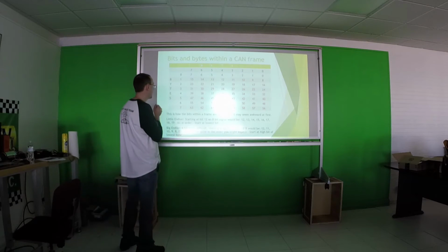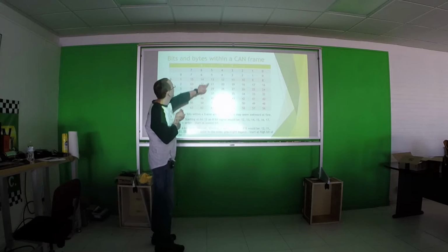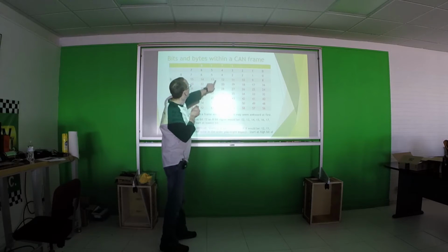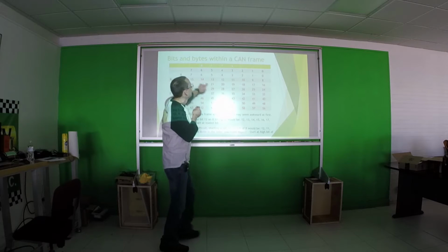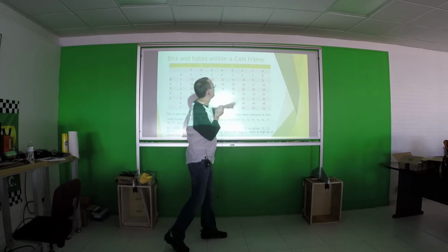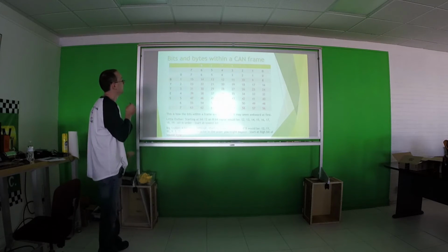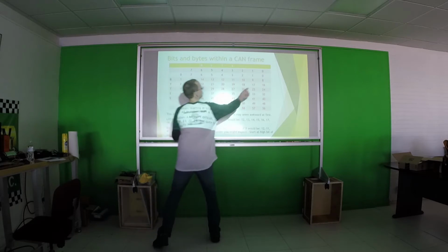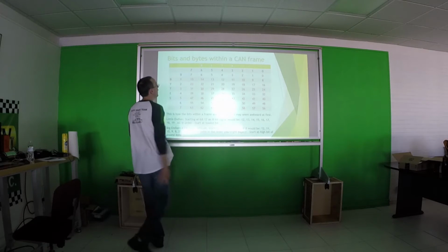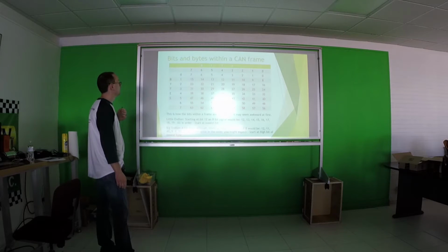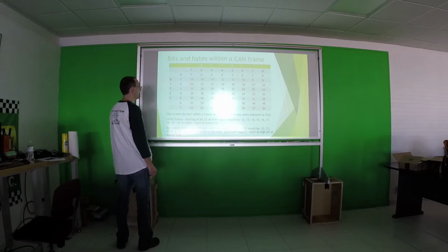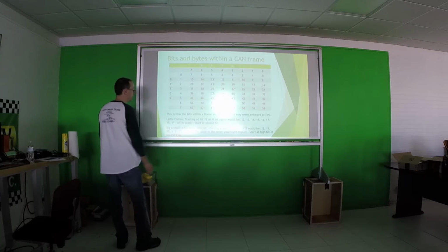And in a DBC file, complicated as it seems, if you start at bit 12, let's say up here, and you're going to store an 8-bit number, which unfortunately they sometimes do, this will go 12, 13, 14, 15, start back over here, 16, 17, 18, 19. That's where the data will be stored in little endian mode in DBC. You hope that they won't do that, because normally if you store an 8-bit value, you'll say start here and end here, and it doesn't really matter which direction you start counting, it's all in 1 byte. But they do store them, and I'll kind of show that. Sometimes they store values across different bytes, and then this difference comes in little endian versus big endian.